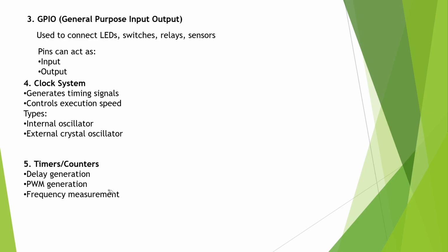You have to control the PWM signal. The PWM signal will automatically control the power delivery to the motors, and it will control the speed, high and low. Sometimes you want more speed in the motor, and then you have to set the duty cycle accordingly. It works on the duty cycle. Go through PWM generation in detail: what is the duty cycle?